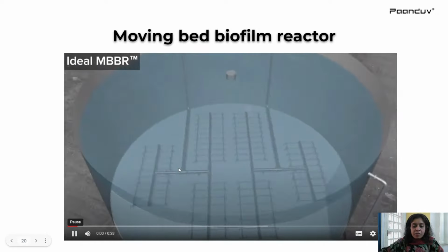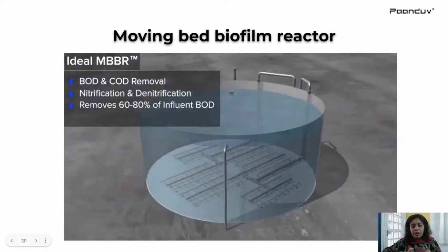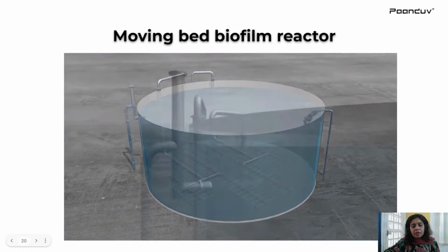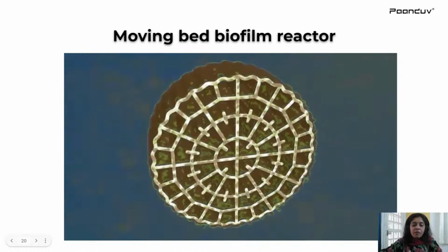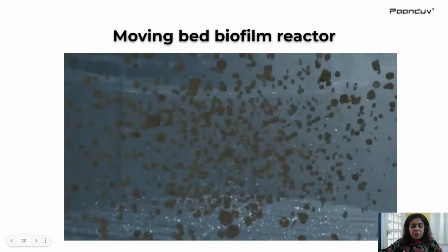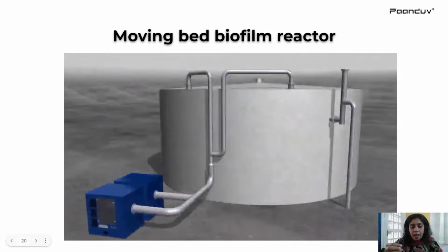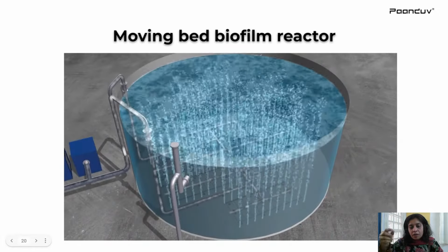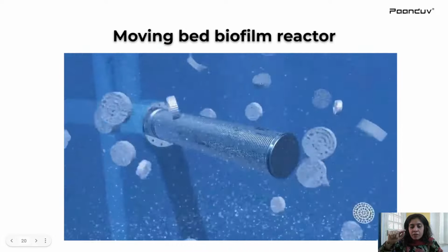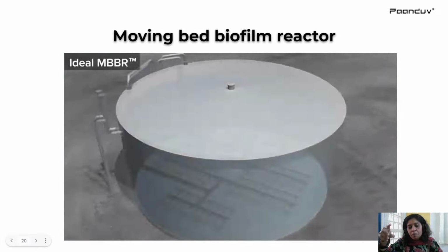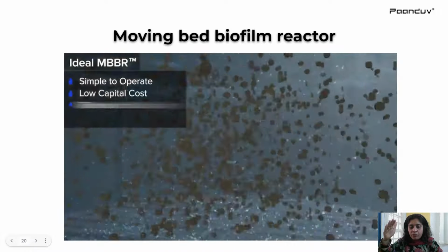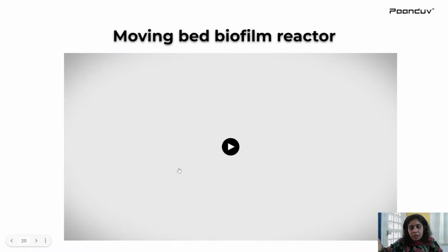So this is kind of the aeration chamber that we were talking about earlier. The moving bed biofilm reactor will have a higher efficiency than the previous one. Even if there is a disturbance in pH, because this biomedia has different layers of biofilms, if there is a pH modification, the first layer is eliminated. Even then, you have a good enough separation efficiency associated with this process.